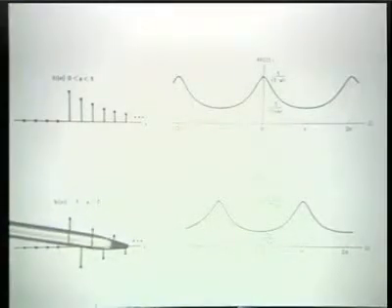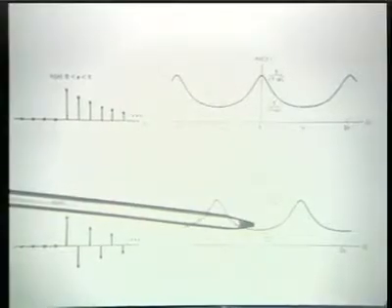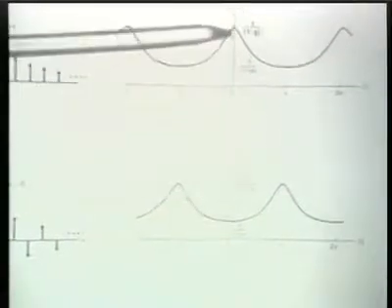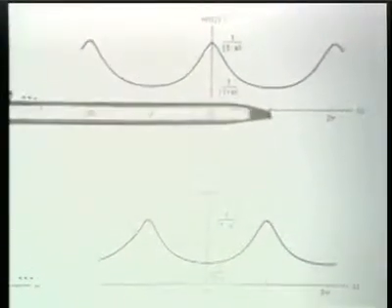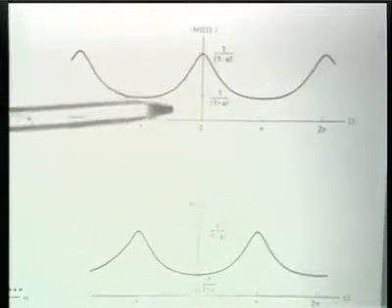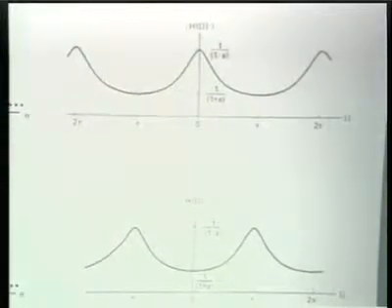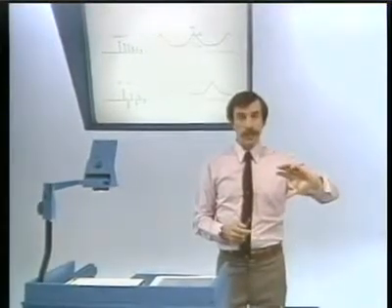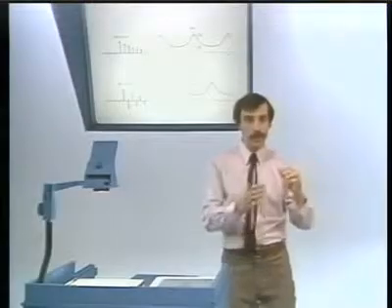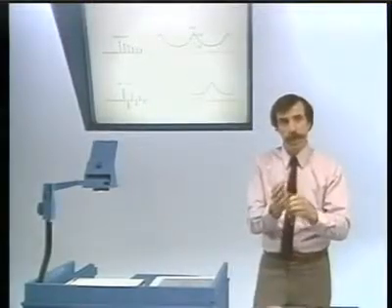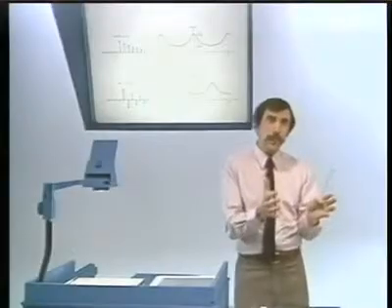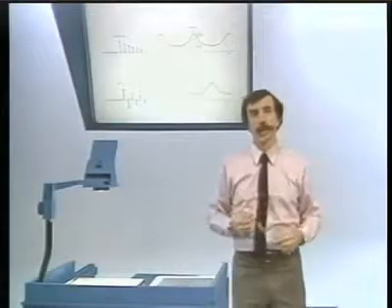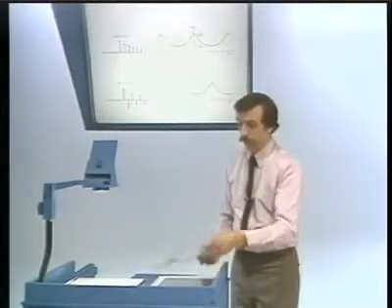And the Fourier transform of that, you can now see and verify also algebraically, if you'd like, is identical to this spectrum, simply shifted by pi. So it says, in fact, that multiplying that impulse response, or if we think of a positive and a negative, that is algebraically similar to multiplying the impulse response by -1 to the n. And in the frequency domain, the effect of that essentially is shifting the spectrum by pi. And we can interpret that in the context of the modulation property.